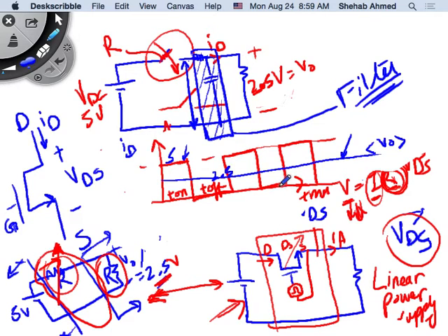If you do that, and you add this filtering stage, assuming you're able to design a proper filtering stage, right? Then what do you get at the output? You get this nice smooth waveform. Is it going to be as nice and as smooth as what you get here? No, because any filtering stage will have a cutoff point where you will still have some AC component, because again this is a pulsed waveform.